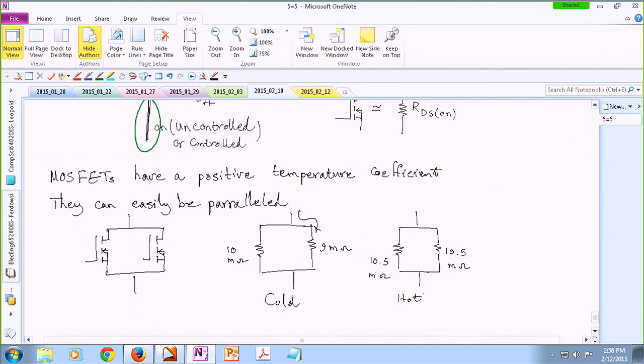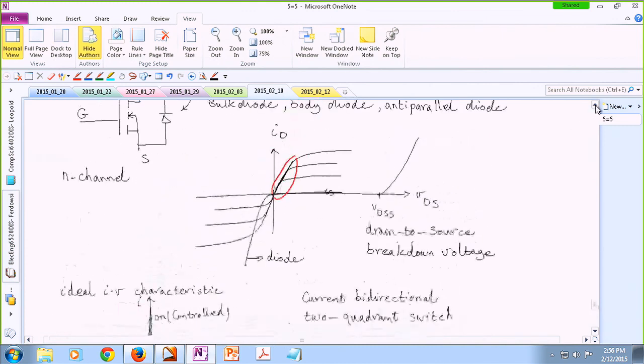All right. So far in this class, yes? When the temperature increases, the resistance increases, right? So the characteristic curve will also change a little bit. That's right. So if you want to talk about the effect of temperature on this characteristic, you can actually get a PhD degree. How this characteristic is going to change by temperature. You're right. But yes, the most obvious observation that you may have is the slope of this RDS on is going to change.